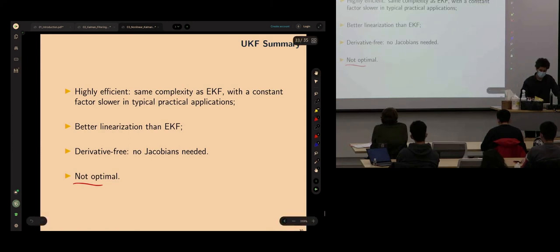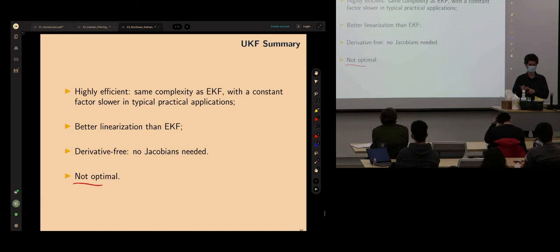So the EKF that I told you about, we can run it at, let's say, 2 kilohertz. 2,000 times in 1 second, this loop will repeat on, let's say, a legged robot. That's a lot of iterations, right? And the state includes position, orientation, velocity, gyroscope biases, accelerometer biases, foot position.